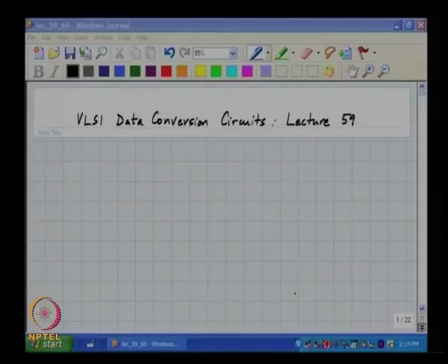Okay. So the culprit therefore is the fact that the individual waveforms that drive the unit elements are derived from the input sequence in a nonlinear manner. So, a fix therefore would be to say I am not going to derive these individual drive waveforms non-linearly.